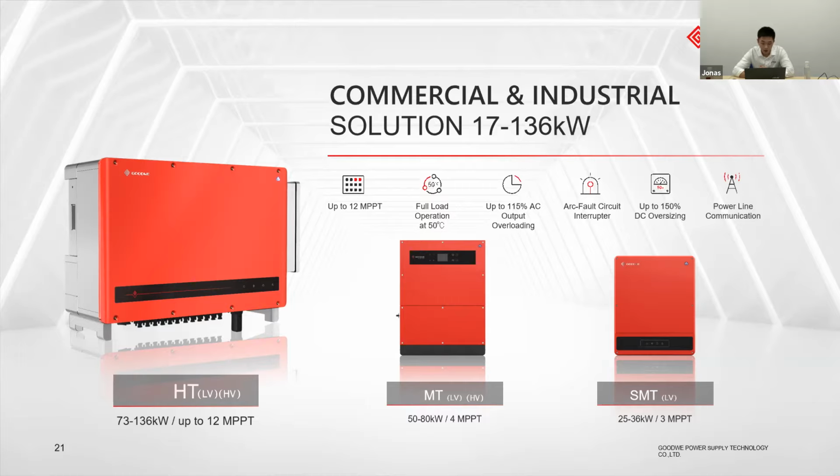In normal conditions, the inverter is used in the normal grid with 400 volts on the AC side. But in some regions, like Belgium, they use a low voltage grid, like 230 volts on the AC side. And in some big CNI projects, they also use 500 volts on the AC side. For all these application scenarios, we have these versions of the HD series and MT series.